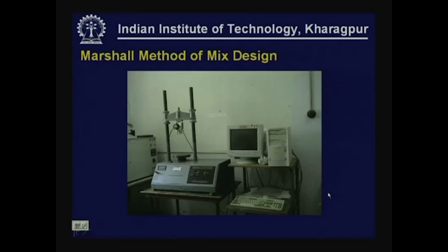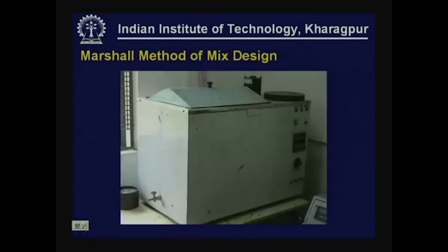This is an automated Marshall testing machine which uses LVDTs and load cells to automatically measure the load and the corresponding deformation, and it can automatically record it into a computer. Of course, we can use other simple equipment also. This is a water bath which is used to maintain constant temperature.